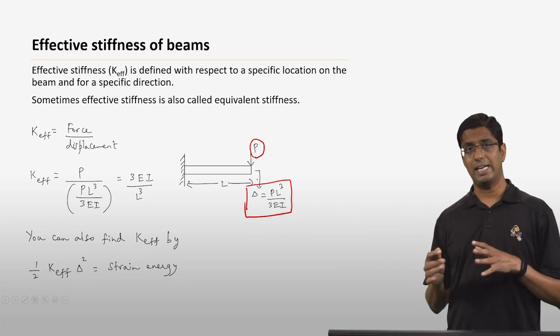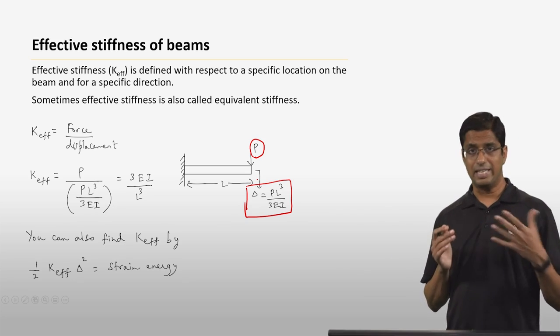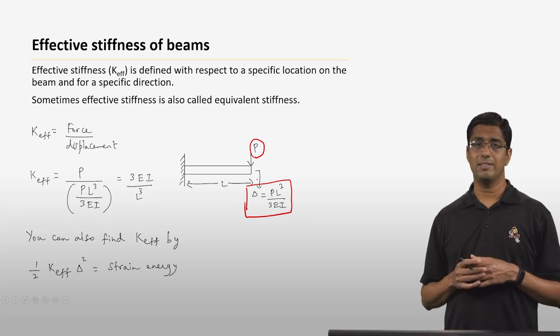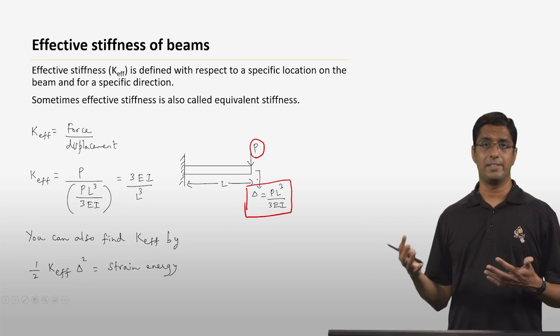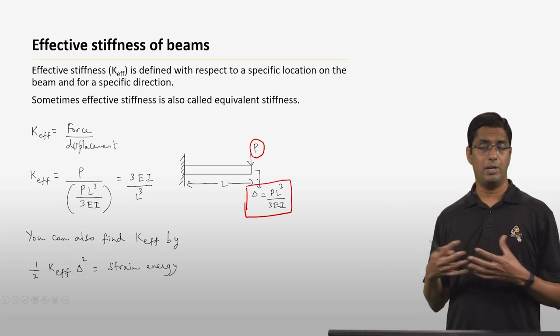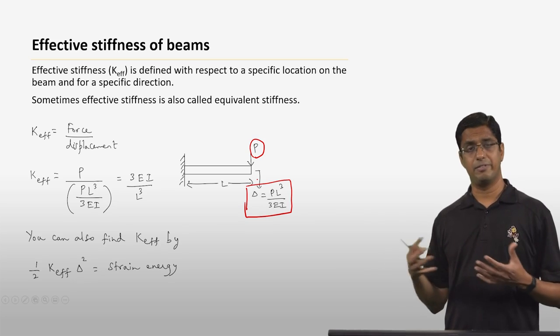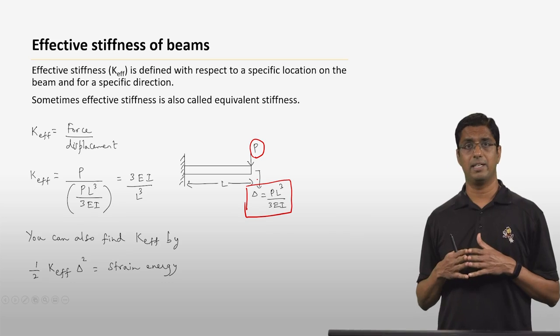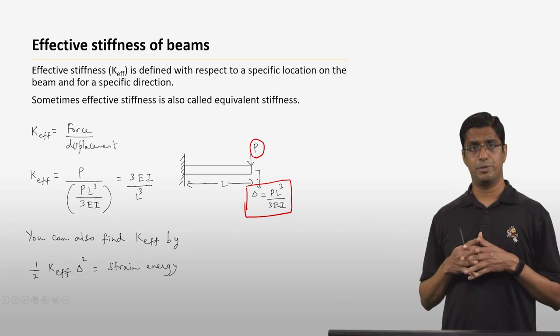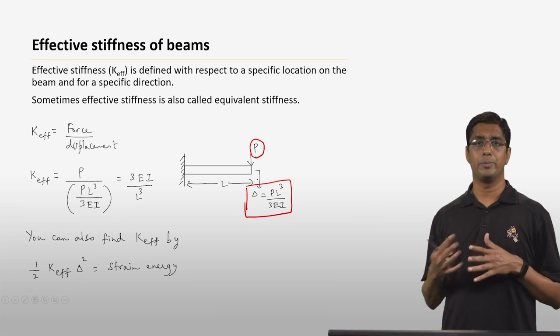You can actually calculate this displacement using Castigliano's method that we have learned in this class, or you can also look at tables that you probably have in a mechanics of materials textbook, which list formulas for deflections for different loading conditions. Anyway, the deflection for this particular cantilever, if you apply a force P at the tip, is going to be PL cubed over 3EI.